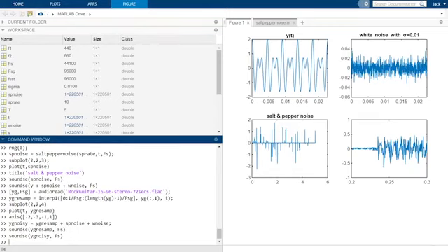Another type of noise is often used in rock music called distortion. Almost all guitar amplifiers have a distortion effect option, and this effect provides a very distinctive rock and roll sound. Distortion occurs when a sound is passed through an amplifier with overdriven gain. The effect is that the amplifier gets saturated. That is, we have met and exceeded its maximum possible amplifier output. This distorts the signal in a highly nonlinear way.